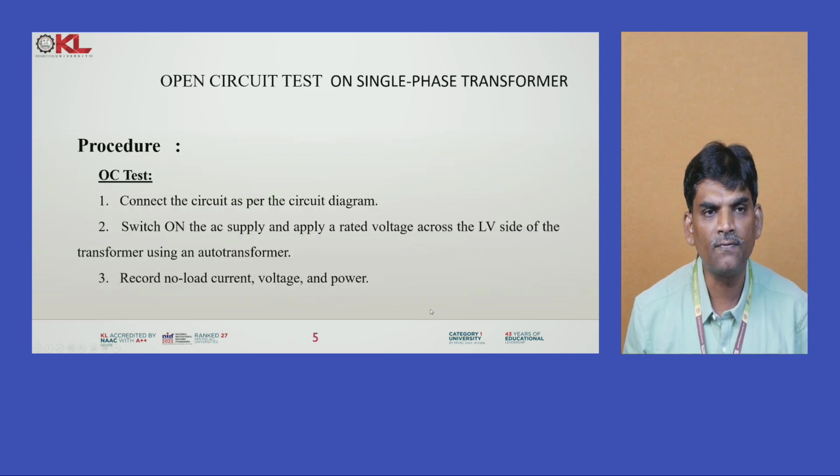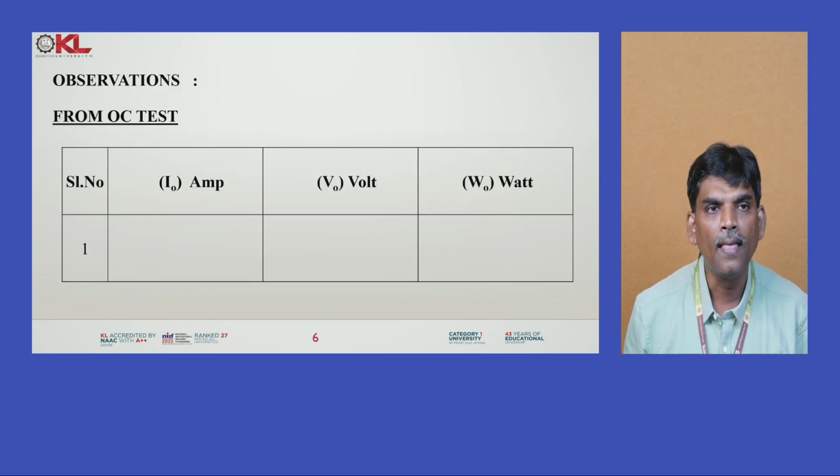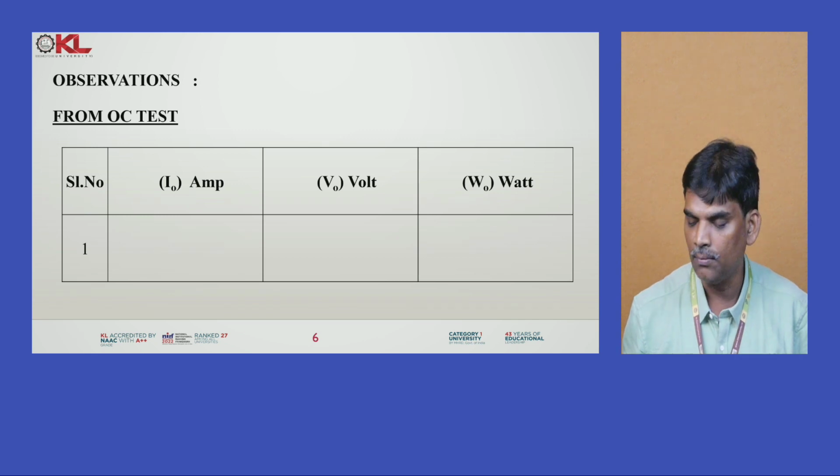Yes, this is the procedure for the OC test. As per the circuit diagram, connect the circuit, switch on the AC supply and apply rated voltage across the LV side of the transformer using an auto transformer, and finally record the no load current, voltage and power. So this is the observation table. Under the OC test we collected this data, VOC, IOC and WOC.